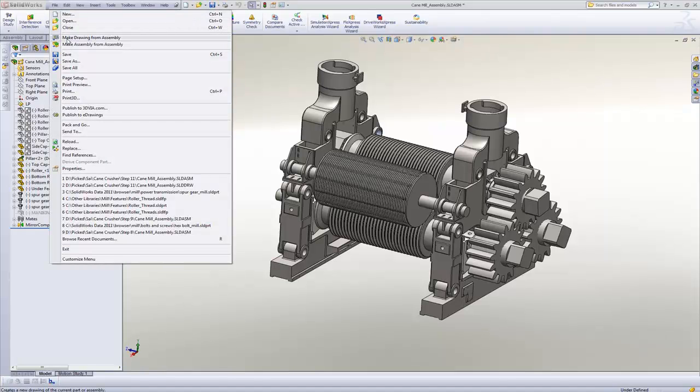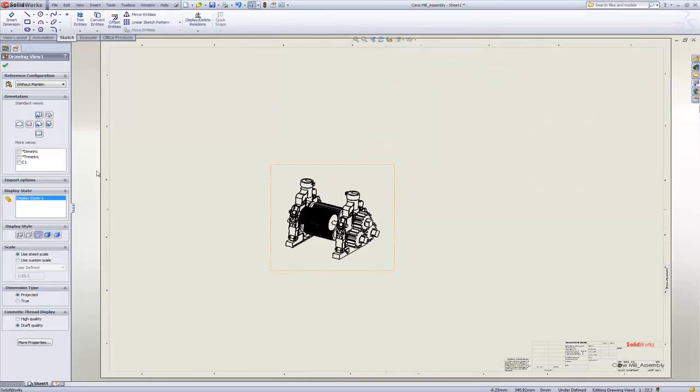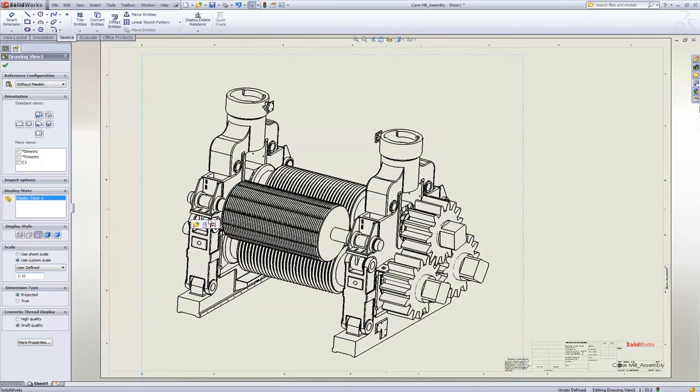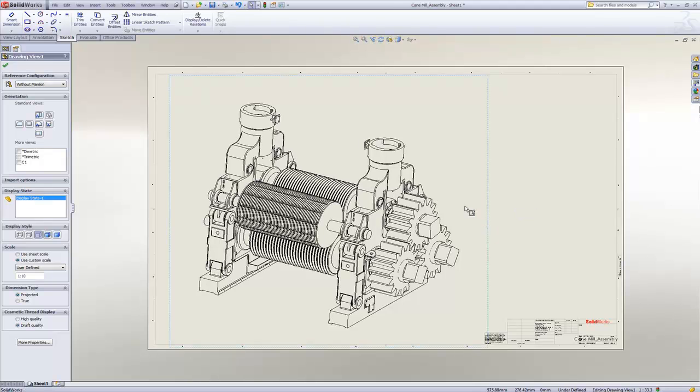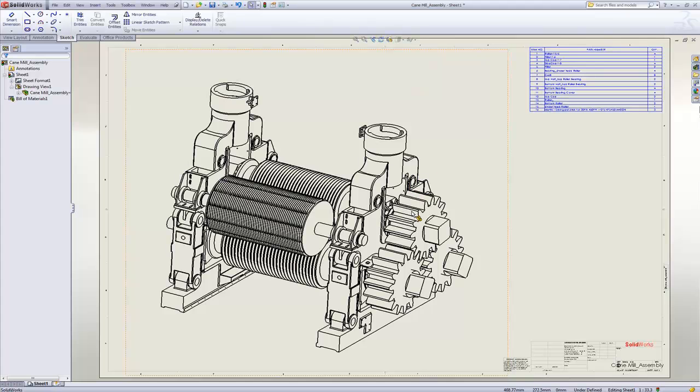As in case of parts, to generate an assembly drawing, we pick the template. View palette will help us to drag and drop standard views. Views can be later scaled to our requirement. It is easy to insert a bill of material. The bill of material template can be customized to call material, cost, weight, and other properties.